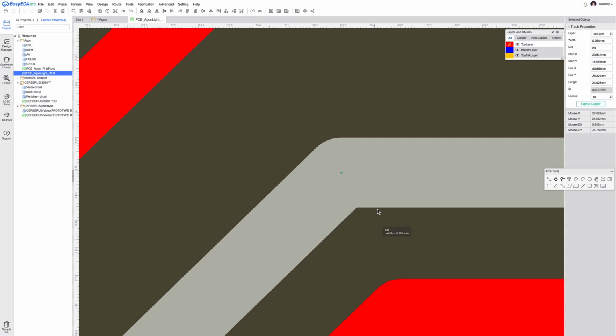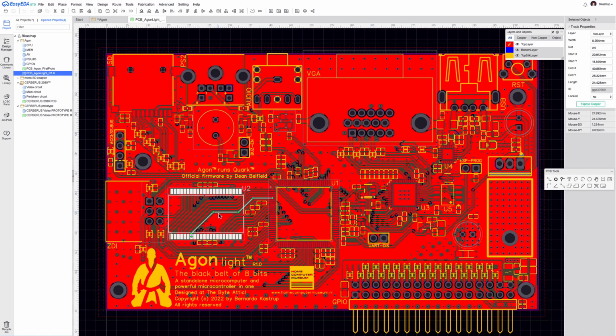Yeah, this width of the trace is lower than this width here across the elbow of the bend. And because the width here is larger, the impedance is lower. So you have an impedance change going through the bend. It would be much worse if you had a 90-degree bend. So to minimize the impedance mismatch, you do it at 45 degrees, and you try to keep the number of bends as low as possible.